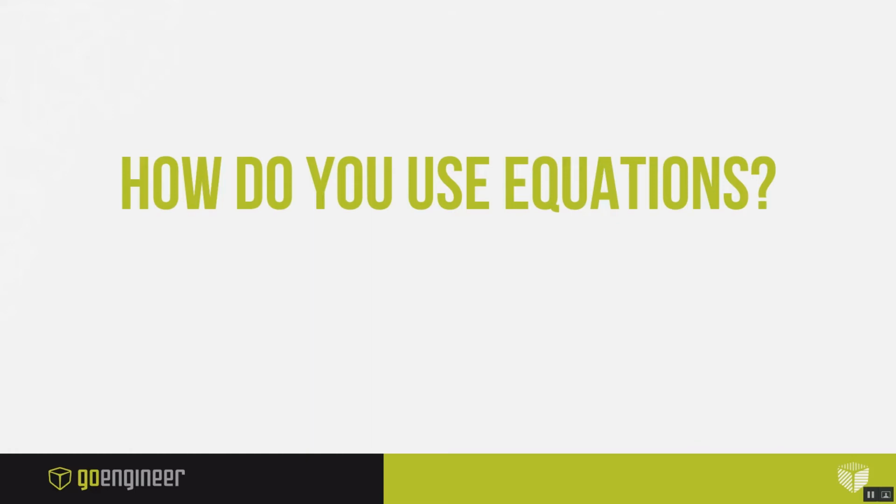If you've ever downloaded anything from McMaster-Carr, they use equations to use one model to drive a whole family of, say, fasteners. Sure. And then we download that, and then we try to simplify it to take it easy on the computer, so we delete everything that's unnecessary. Gotcha. Okay. How about? I've been both spectrums. I've been like top-down models, full equation-driven, and then I've kind of leaned back and do simple part equations.